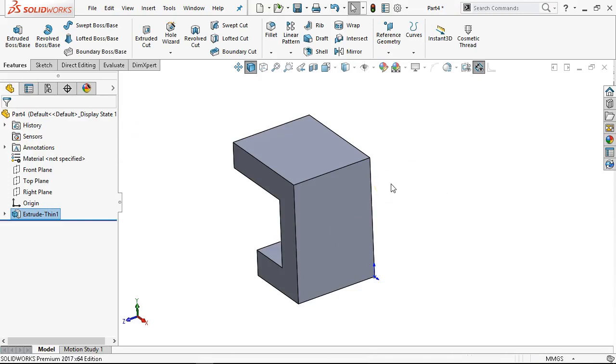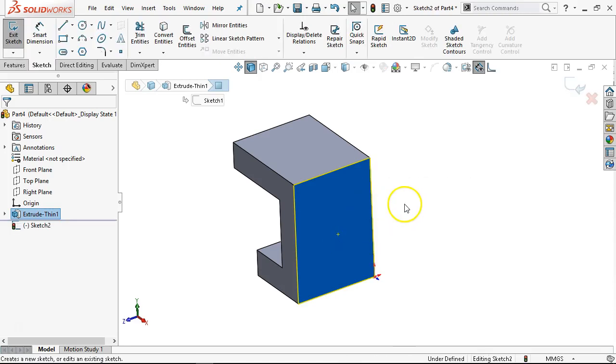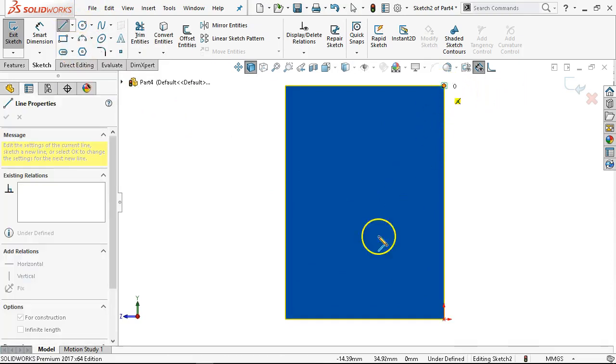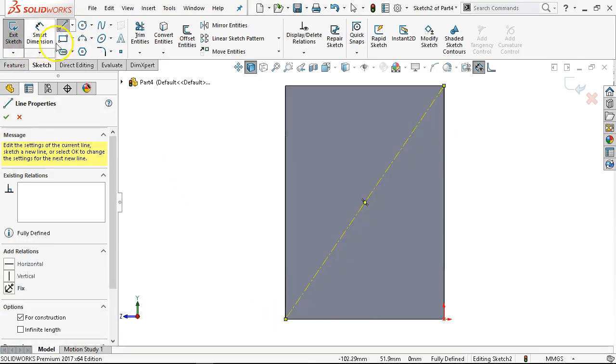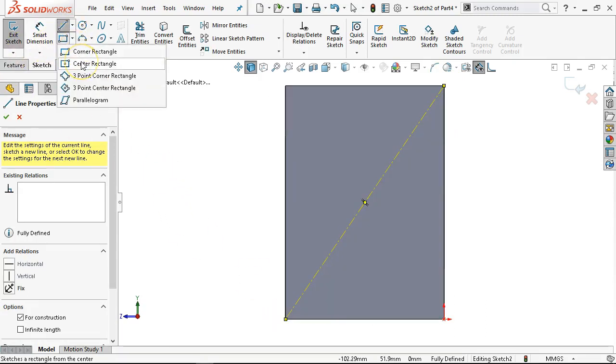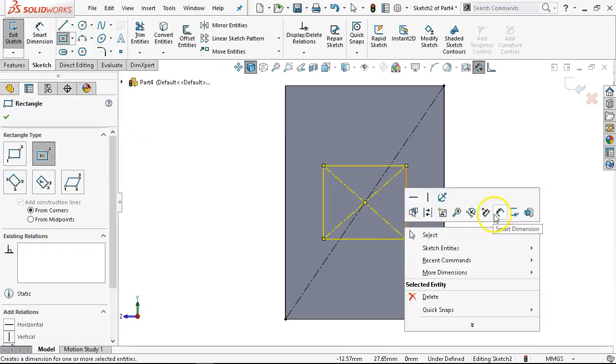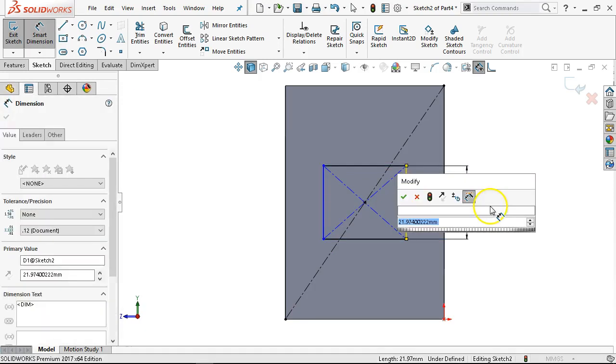All right, so 20 and 25 is 45. 45 and 25 would be 70, so that's centered, and 15 and 20 is 35, and another 15 would be 50. So design intent says I want this rectangle centered on that back face. So I can go center line, and my preference has been to go corner to corner. It usually does not interfere as much with other geometry, but you'll have to try it and see what works.